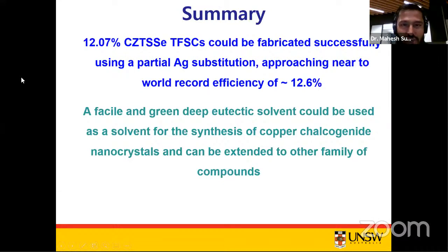So that can be another question. In the case of perovskite, I'm not sure it's a good idea to use CZTSSe as a counter electrode, because you can find many other counter electrodes for perovskite which are really efficient compared to CZTS, CZTSSe or other copper chalcogenide compounds. These copper chalcogenide compounds, such as CZTSSe, CIS, or copper antimony sulfide, are mainly light absorbing compounds with a high absorption coefficient.